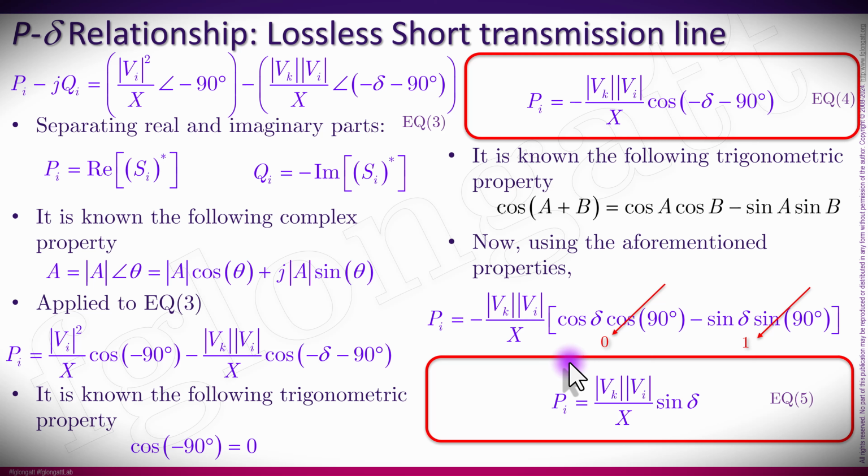You are defining this active power transfer using the series inductive reactance, the magnitude of the terminal voltage, and you must remember this angle delta is basically the phase angle between the sending voltage and the receiving voltage.